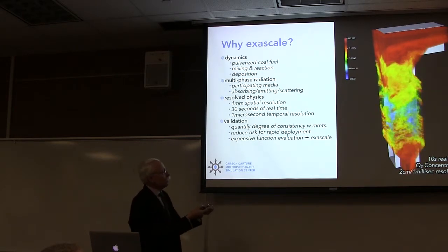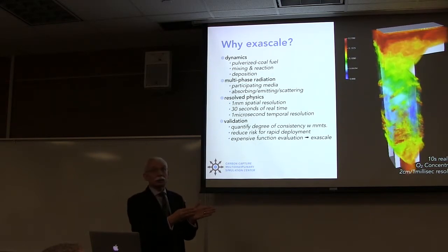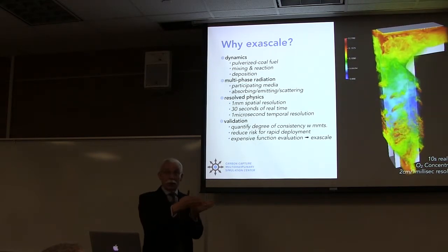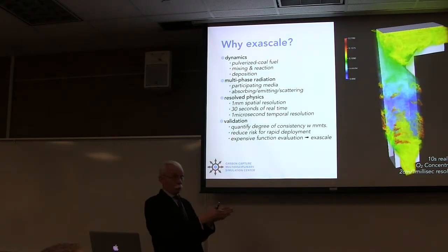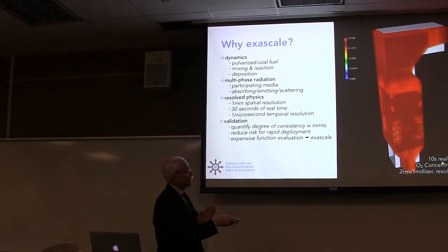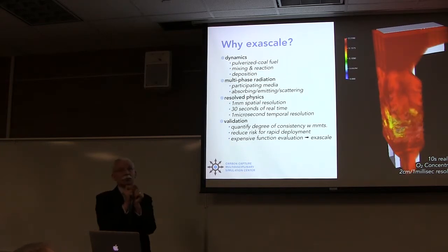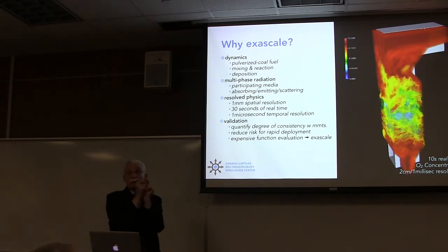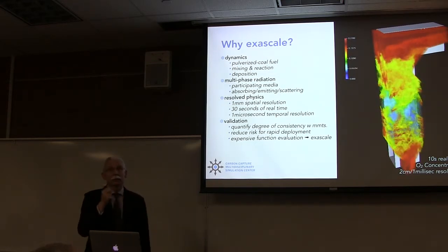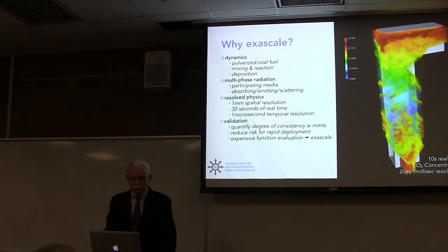This was done with large eddy simulations on 6,000 cores. So this is on a petascale machine, not an exascale machine. And so 6,000 cores used simultaneously for about a week and a half to get this simulation of 10 seconds of real time. And the resolution in the system, for that one that you're looking at right there, is 2 centimeters. So you saw the size of the boiler, and the resolution of the finest scale that we're resolving is 2 centimeters on the side. It's a cube.